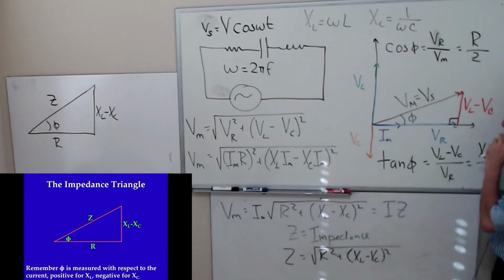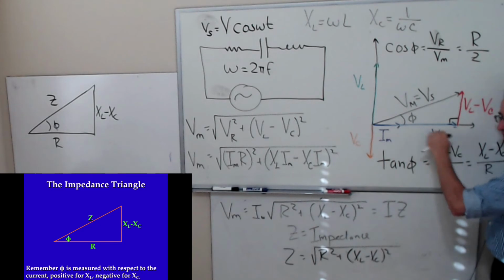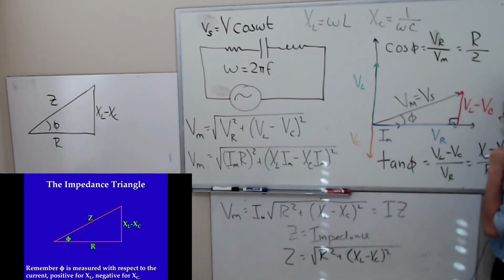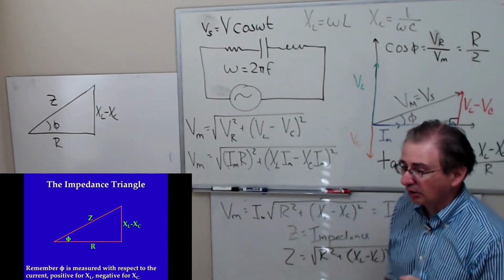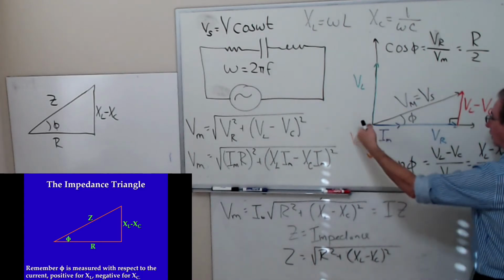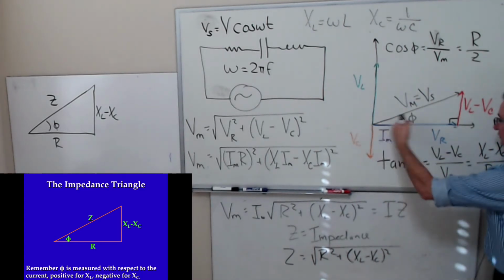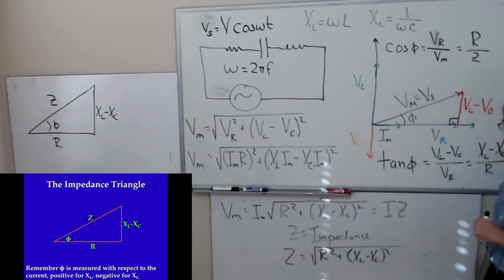And it basically reacts more like a resistor. Whatever's projected on here has to do with elements that act more like a resistance. The projection onto the y-axis represents the reactive part of the circuit. But you can only say that if you draw your total current along the horizontal direction. And I'm not really being precise in saying what this represents along the x-axis.